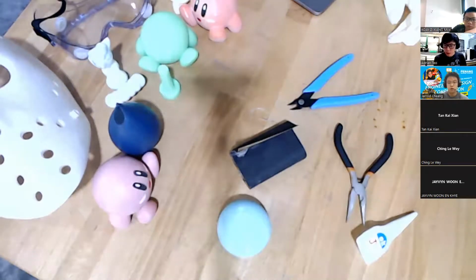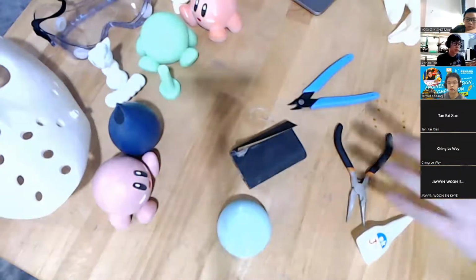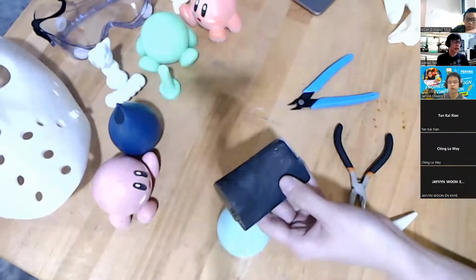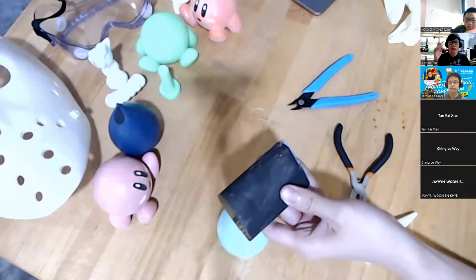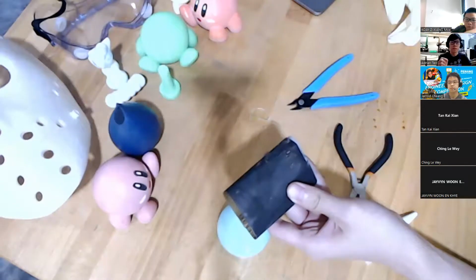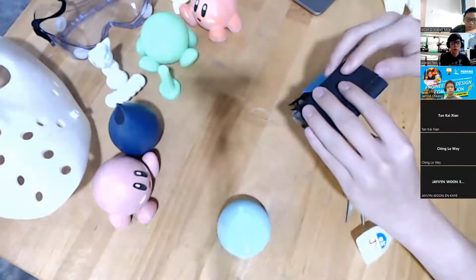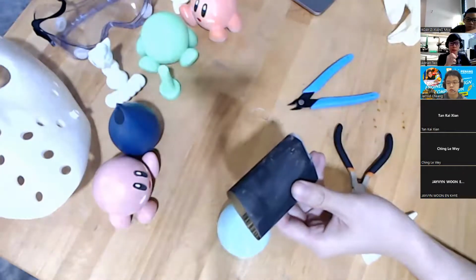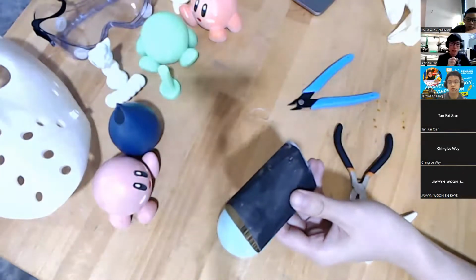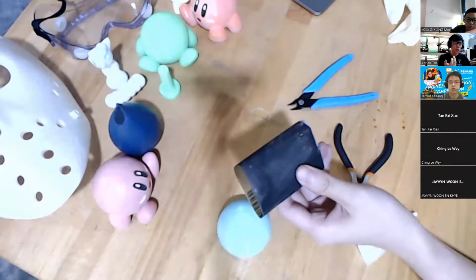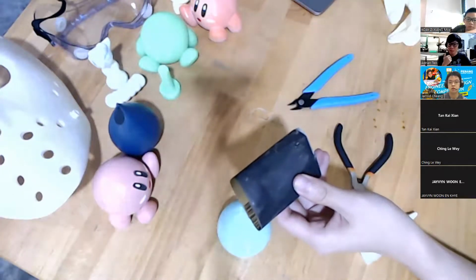Okay, I got one question from Amar Danish. He asks, what is the difference between sanding with or without water? If you sand without water, that's basically called dry sand. And usually dry sand is done using lower grade paper, means the rougher paper. When you sand with rougher paper, lower grade number, the particle is larger, slightly larger. Okay, it won't go through your face mask that easily.